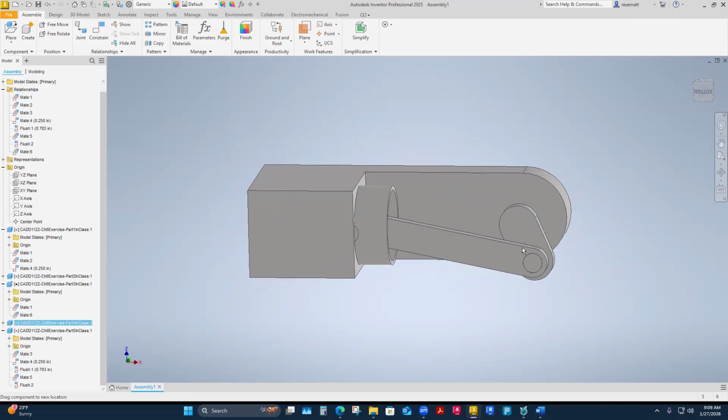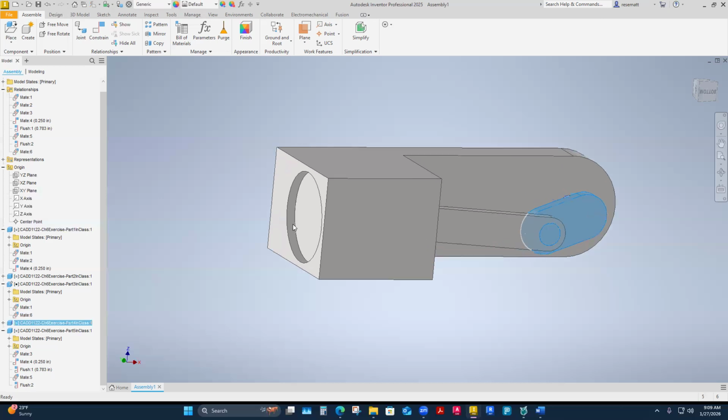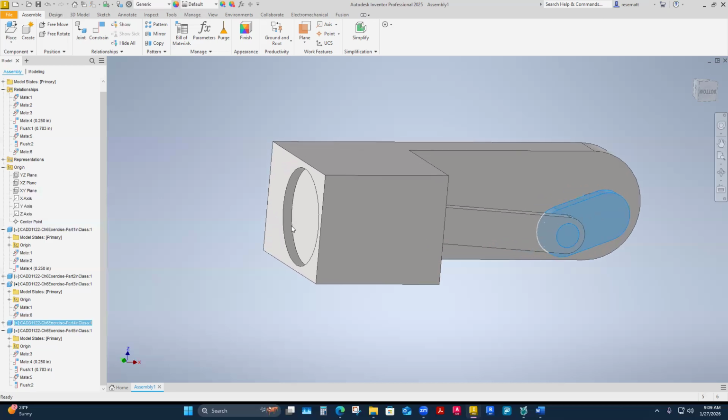And then I can spin this thing here. And now my piston actually stays in the cylinder, and it doesn't come all the way out, which is critical on a piston, and it doesn't go all the way to the back side as well, which is also critical. So technically, yeah, that was the right adjustment on this particular size.